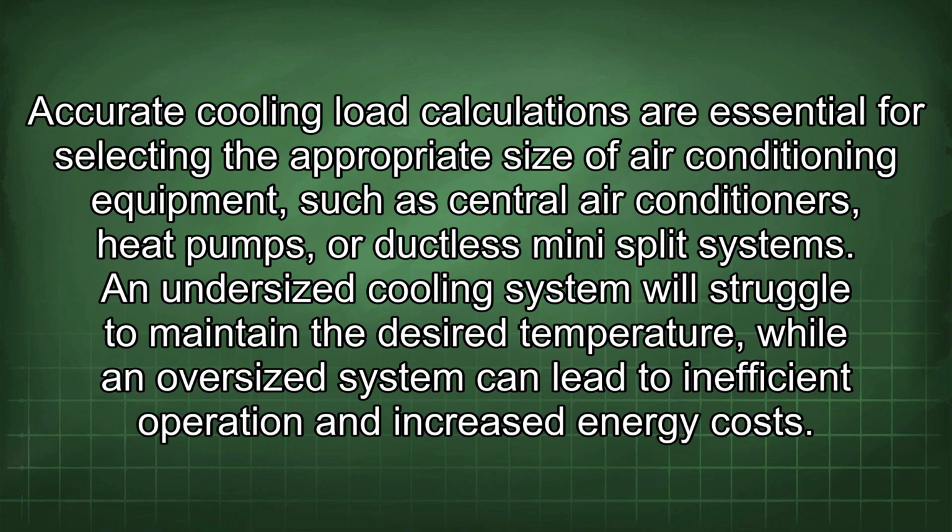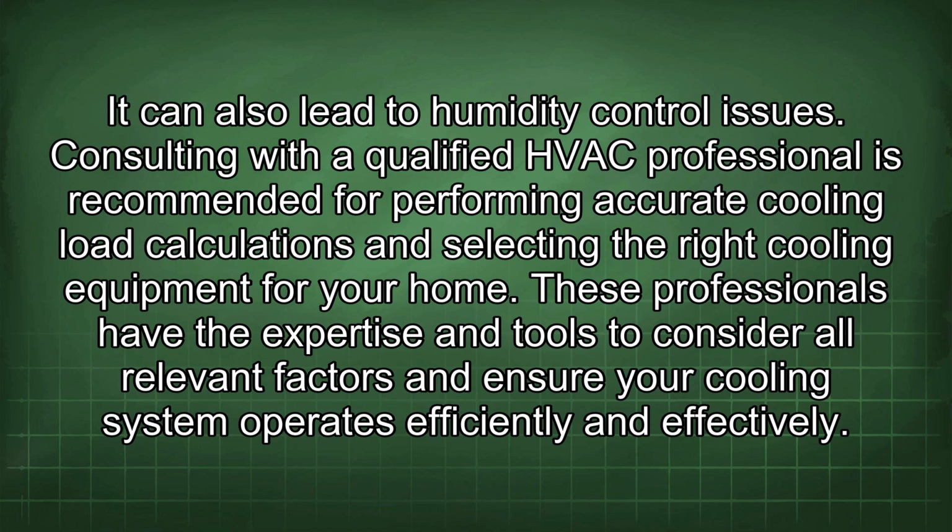Accurate cooling load calculations are essential for selecting the appropriate size of air conditioning equipment, such as central air conditioners, heat pumps, or ductless mini-split systems. An undersized cooling system will struggle to maintain the desired temperature, while an oversized system can lead to inefficient operation and increased energy costs. It can also lead to humidity control issues.